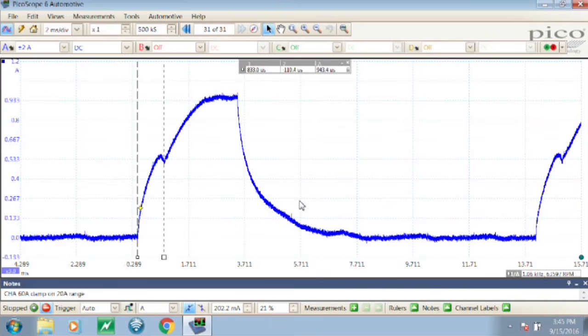And the injector's current flow, 978.3 milliamps. So we have a variation in injector flow that was done on a flow bench, that the knockoff Bosch injector flows like a 30-pounder.